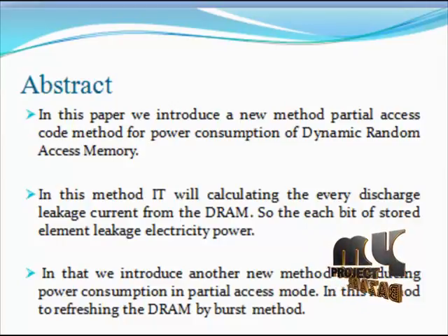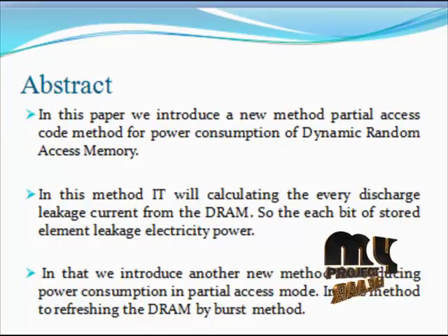We propose a new method to reduce the refresh power consumption by effectively extending the memory cell retention time. Conversion from 1 cell bit to 2 power n cells bit reduces the variation of retention time among the memory cells.